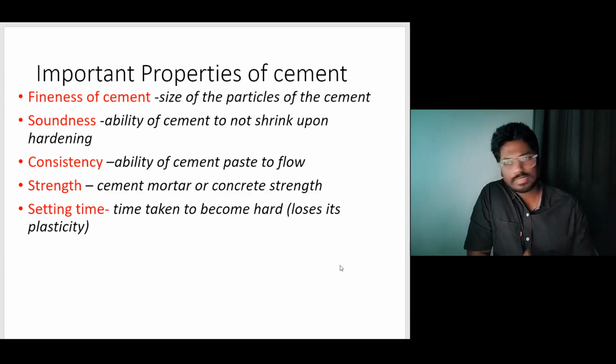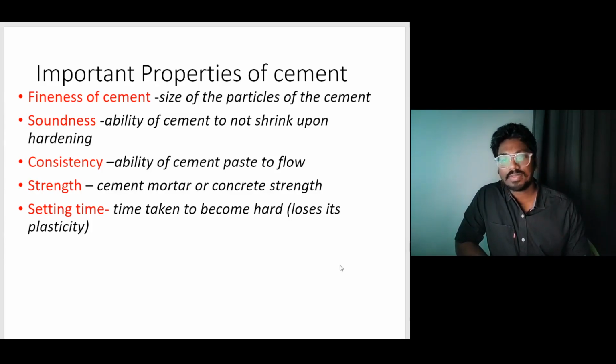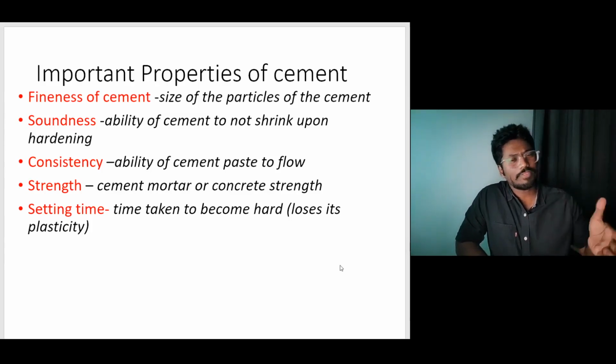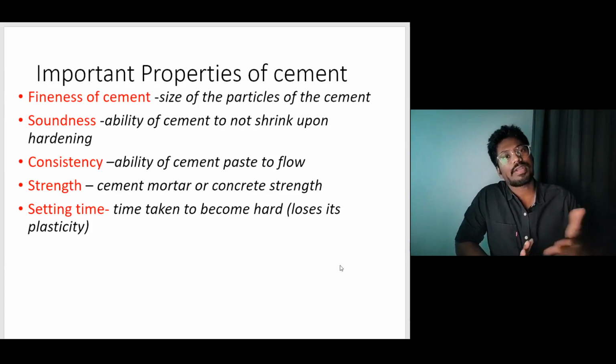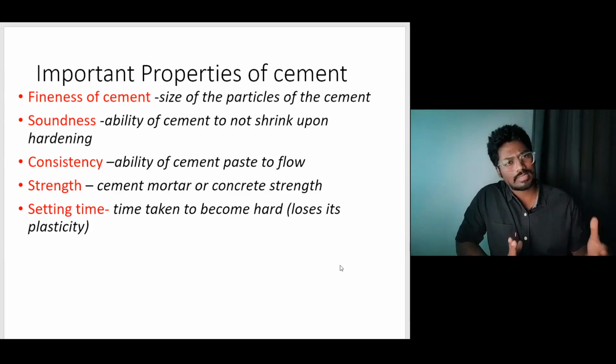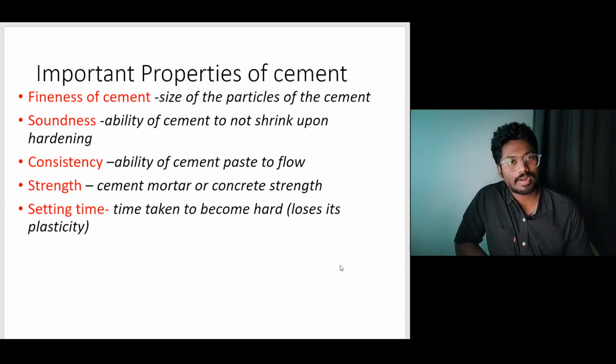Strength, like I said, cement mortar also has a strength which is directly related to the overall strength of the structure. Setting time, the time taken to become hard or lose its plasticity, is called setting time. Different cements have different setting times. We have different applications for a delayed setting time or a quick setting time. So that's something of a much deeper note. But in general, as an important property of cement, setting time will also play a major role in defining the hardness or the strength or the application of that particular cement or structure.